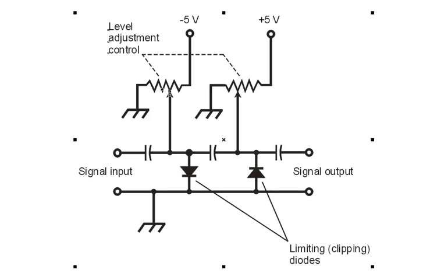And the schematic diagram, figure 5-12, shows an actual arrangement where we're talking about this variable bias across the input and output terminals so that we can regulate the extent to which these diodes clip the signal.